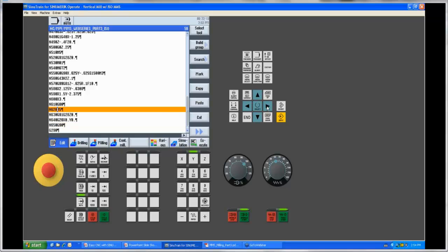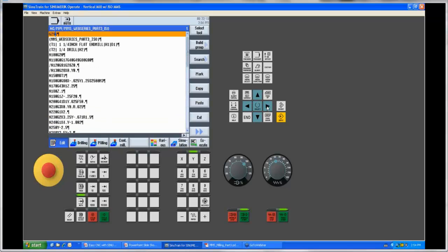The other thing I always recommend to people is don't use this mode if you're going to develop a post. It's a very easy crutch to get into to say, hey, I have a FANUC post already. Let me just add a G291 to the beginning and end of the program, and I'm good to go. There are plenty of advanced functions within our control that give us pretty high-level capability. The problem is if we're only ever running in this ISO mode, we can't take advantage of them. So you're not really using the control to its full capabilities, especially when you get to complex machines, 5-axis machines, multi-technology or mixed technology machines like turn mill or mill turn. Those are areas where, use this sparingly.